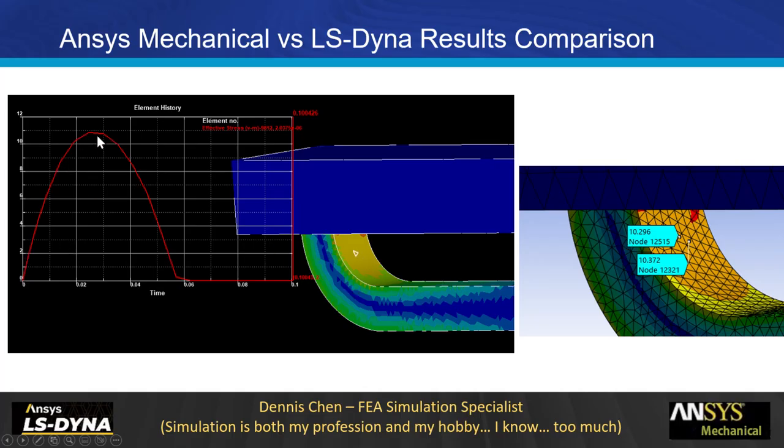You can see the peak stress is a little bit less than 10, maybe 10.6, 10.7, 10.8. On the mechanical side, I probed the nodes around the same area. The stress is around 10.3, 10.4, right? So you get pretty much the same stress in the same location between the Dyna model and the mechanical model. Basically telling you that you have very comparable results in both simulations, right?